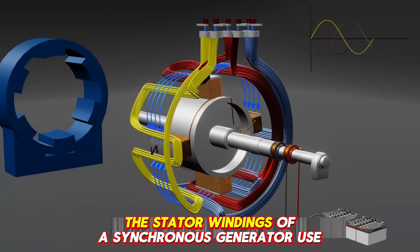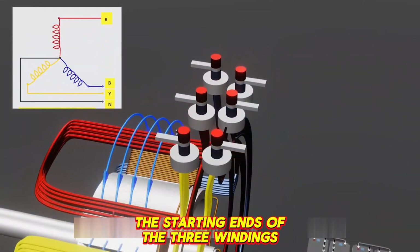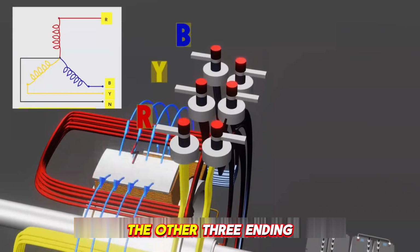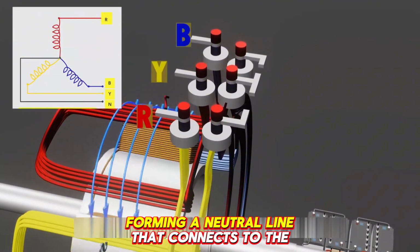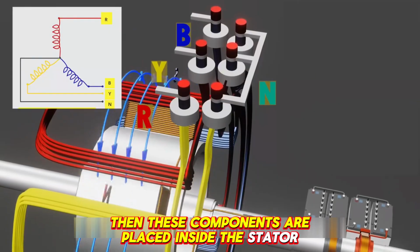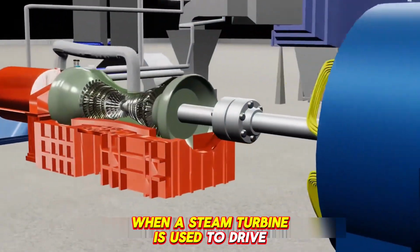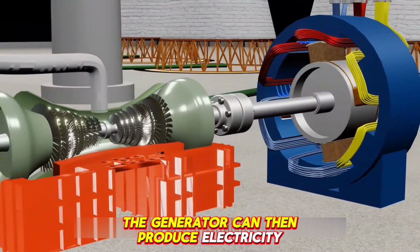The stator windings of a synchronous generator use a star connection. The starting ends of the 3 windings are connected to the live wires of the 3-phase AC. The other 3 ending ends of the windings are connected to each other, forming a neutral line that connects to the neutral wire. Then, these components are placed inside the stator frame, and a generator is assembled. When a steam turbine is used to drive the generator's rotor at high speed, the generator can then produce electricity.